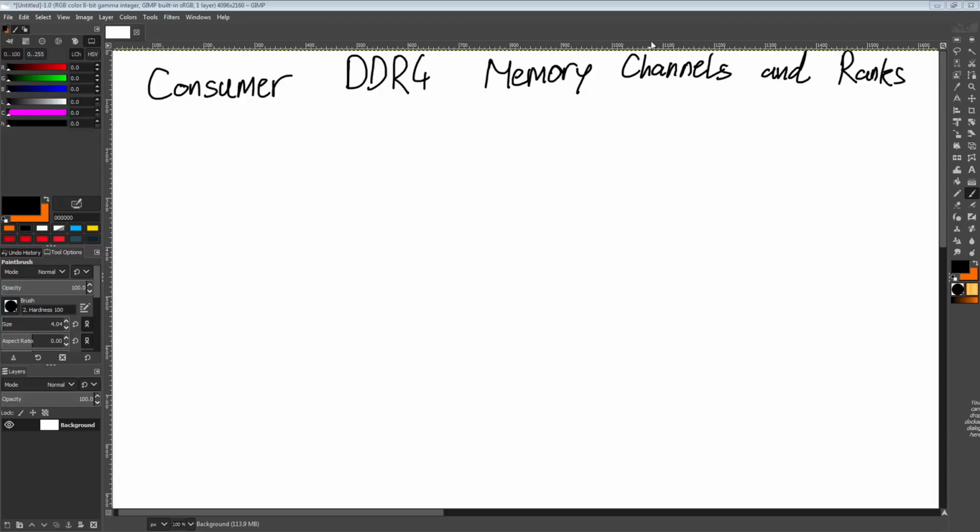Hey guys, Buildzoid here, and today we're going to be talking about memory channels and ranks on consumer DDR4 memory, because I've basically had people ask me lovely questions like, can you run dual channel off a dual rank memory stick? And basically, no, you can't.